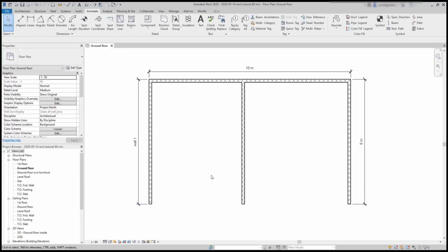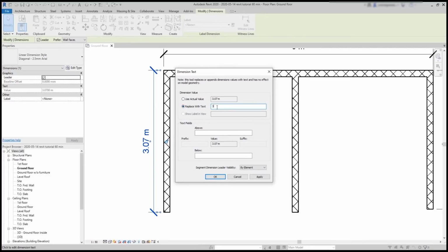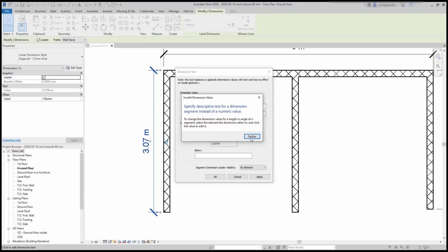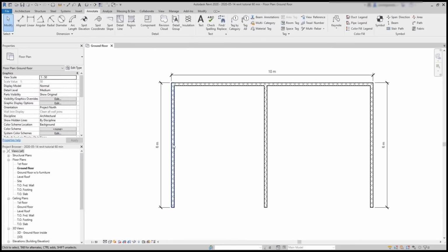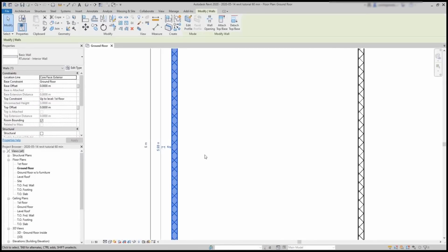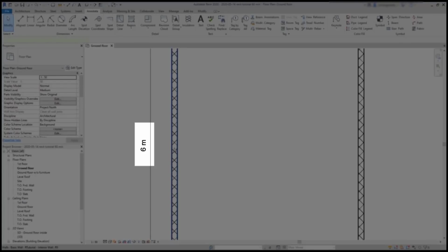But have in mind, if I want to cheat or just change the actual value to an approximate number, the program doesn't let me do it. It says that I cannot replace a value with a different value. Basically, to modify the length of this wall, I have to select the wall first and then click on the dimensions in the same way that I do for the temporary ones. Notice also that when the dimension is editable, the color changes to blue.